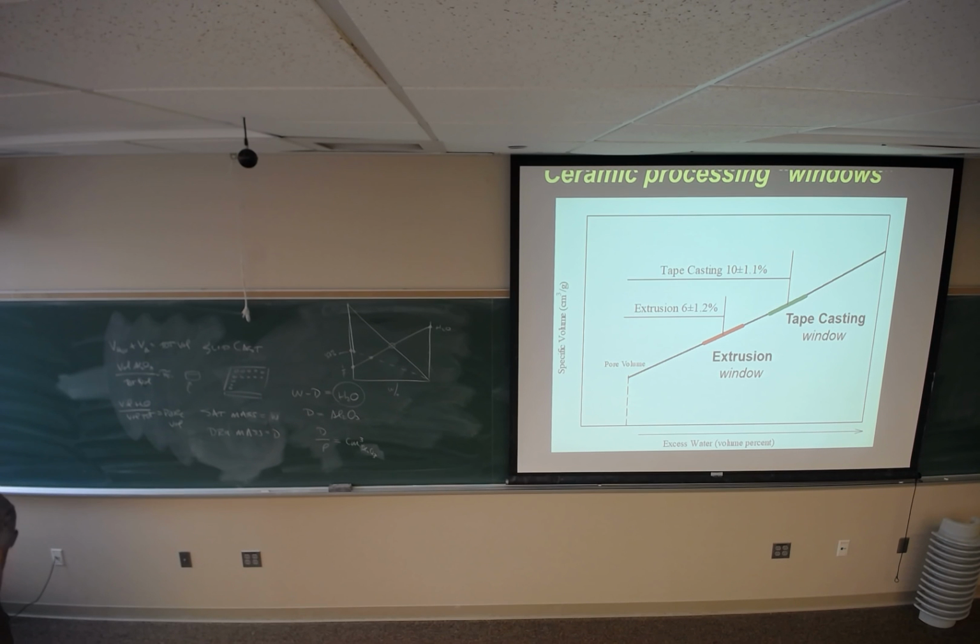So what you do is you take your pellet right out of casting and you weigh it. So just how long would you wait after casting? You pour it in and wait 5 minutes or something? Or you wait until there's no more fluid, no more suspension left on the top. Flocculated casting is quick. What's your time? About 10 minutes. Dispersed casting is slow. I'll show you why in a minute.